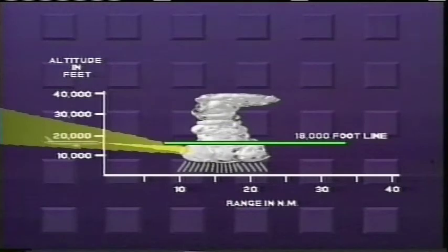If your flight path is below 18,000 feet AGL and you use the recommended tilt management procedure, you can use any display range and not be in danger of overflying a dangerous storm. In that case, simply select a range which will give you adequate warning time so that you can make an avoidance maneuver in a timely manner. At the higher altitudes, it is important to remember that you are flying above the most reflective part of the storms, and consequently, you will require a significant down tilt to make certain no storm goes undetected.